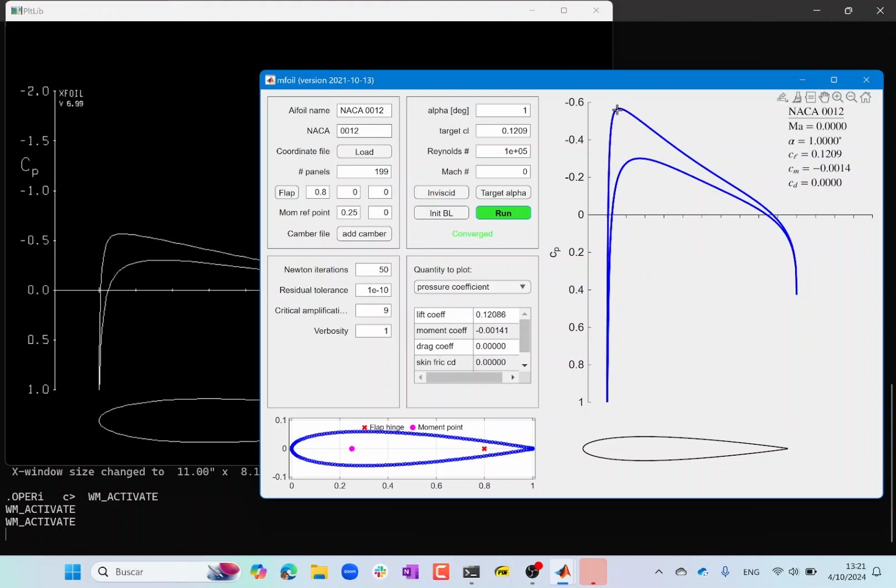right? I mean, the peak is actually not here because the pressure curve goes down further here, right? The peak is probably closer to the leading edge than the peak suction, the peak of the pressure difference. And this is basically an approximation, or I should say, the function we saw in lecture today is an approximation of the pressure difference we see over here, right?